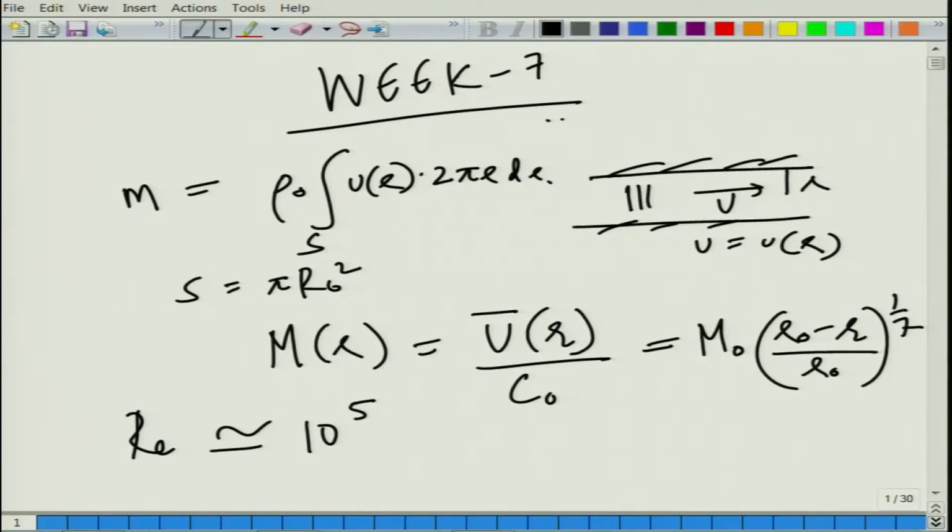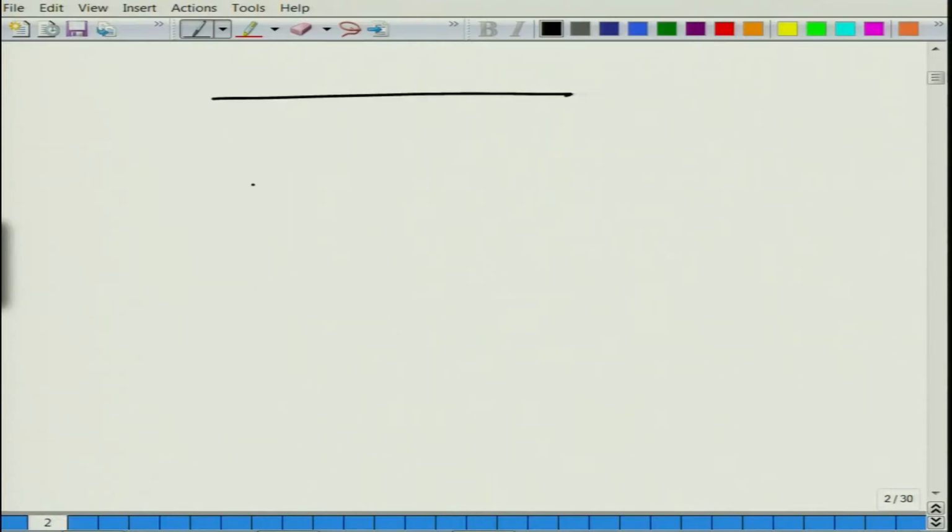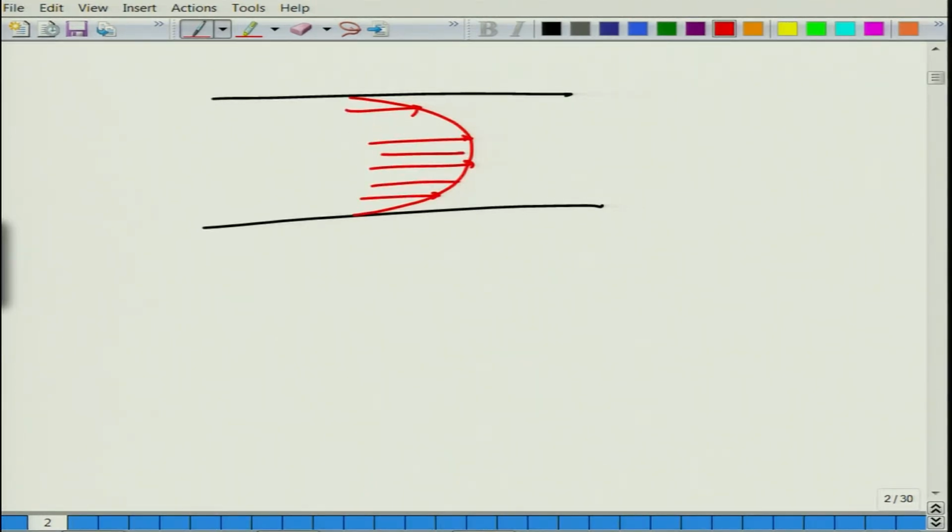This is typical in exhaust pipes of internal combustion engines, and what we have also observed is that the average value of the Mach number is typically about 0.85 times the Mach number observed right at the center. So, the flow profile will be something like this, if you allow me to draw an exaggerated view. So, here we are talking about M naught, and here the average Mach number is 0.85 times M naught.